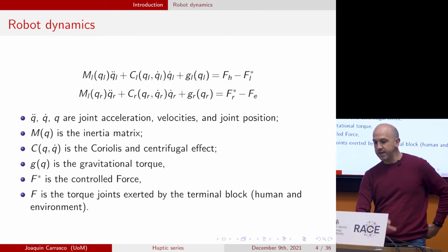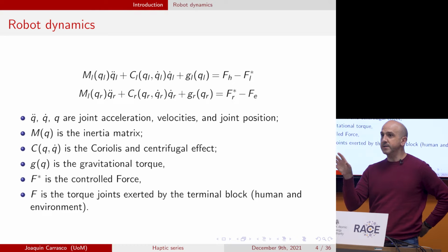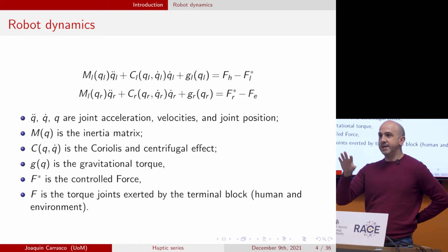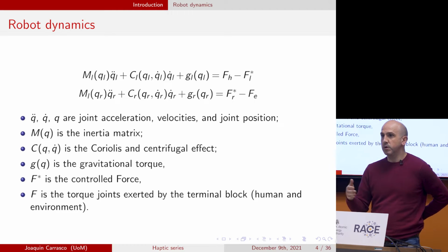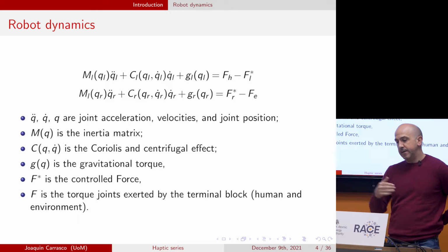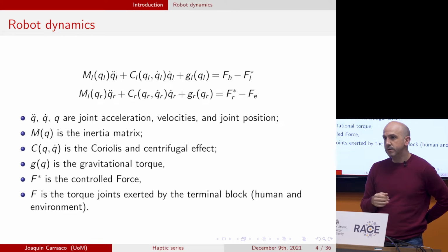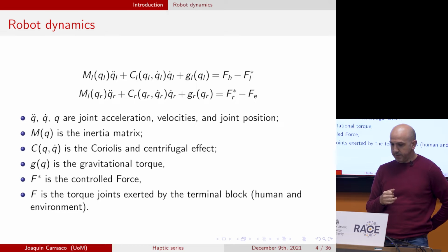This is why we are splitting these forces in two parts. One is just generated by the contact of the robot with the environment. The other one is the force that the controller will normally be generating, or that every joint is going to be producing.